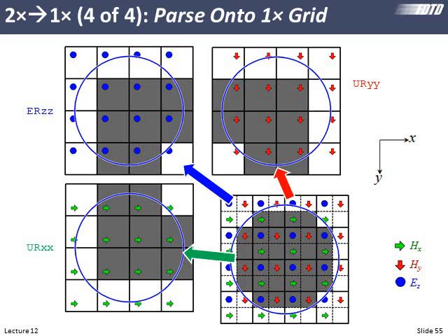So here goes. Here's where we are and how the field components lie. To calculate epsilon ZZ, these exist where the EZ components exist. Remember, the EZ components are the blue circles here. So there's an EZ here, an EZ here, an EZ here, and an EZ here. None of those are in dielectric. So notice the whole first row is not in dielectric. Then we go to the second row: no dielectric, dielectric, dielectric, dielectric. So up here we just fill in the entire cell: no dielectric, dielectric, dielectric, dielectric.